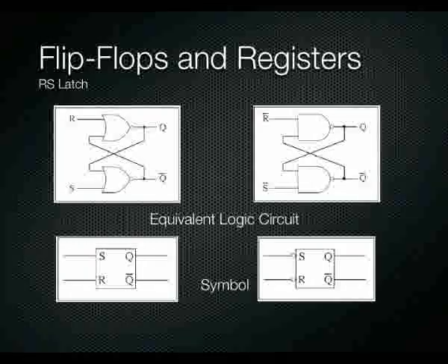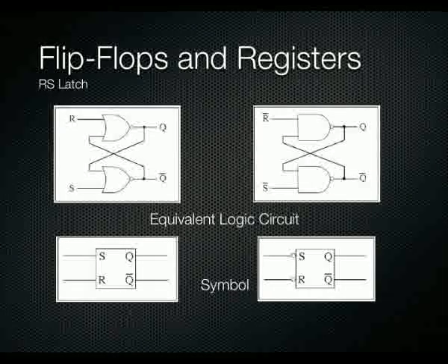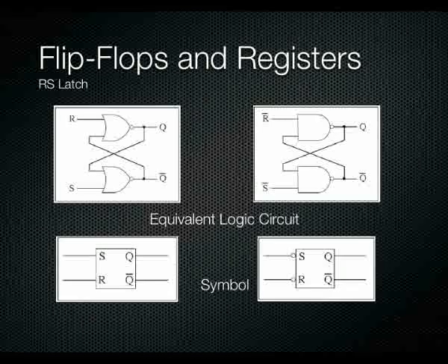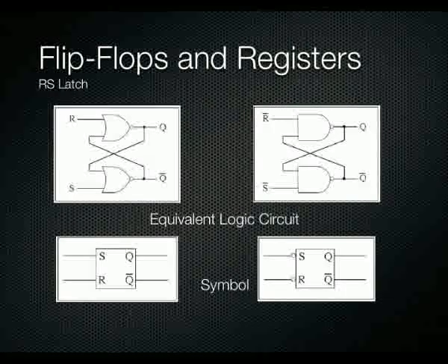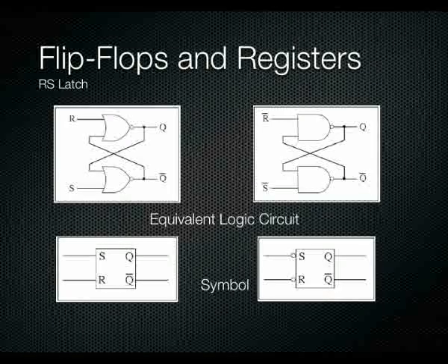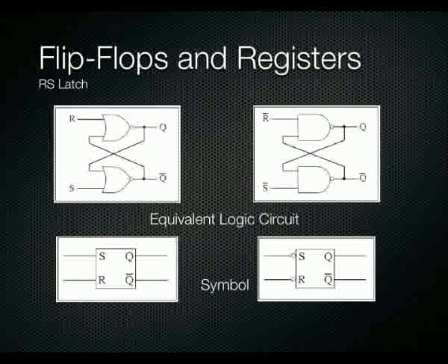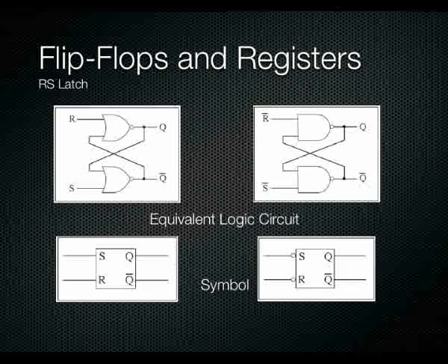So flip-flops and registers are a very important component in digital logic because flip-flops are effectively our memory elements. These are basically logical circuits that remember. Okay, and the simplest flip-flop that we have is the RS latch. The RS latch comes in 2 forms. You can make it from NOR gates or you can make it from NAND gates, but either way they effectively work in the same way.